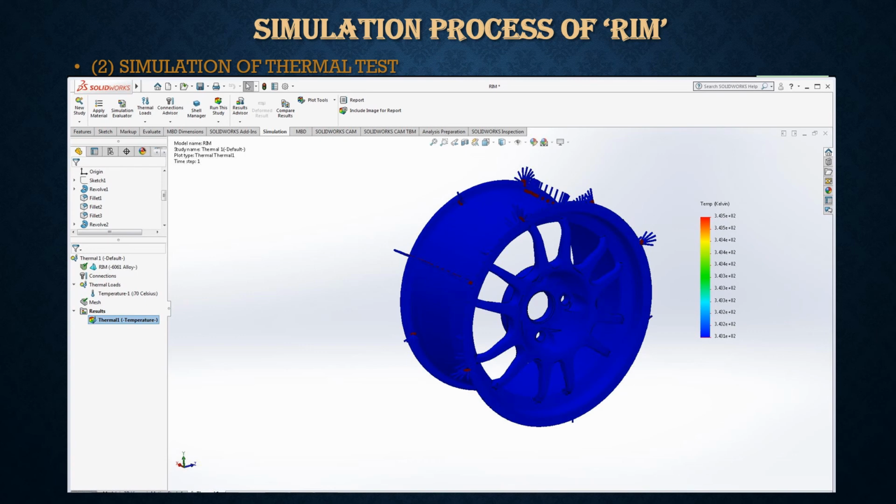Then thermal load and select temperature, then select thermal condition, part on part. The thermal temperature that I use for my material is 70 Celsius. And then create mesh, run the study, and it shows the result of the thermal.